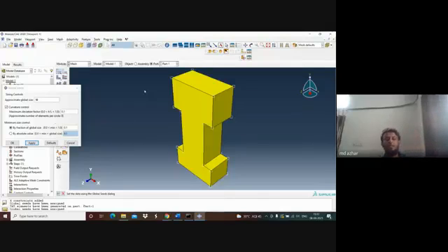Now you can see this is here and here. Okay, so you can see only 4 points are meshed. This means this is too big a mesh size. Our geometry is not that big, so it can't accept approximately 10 as the global size. So now let us try to decrease it and see what happens.